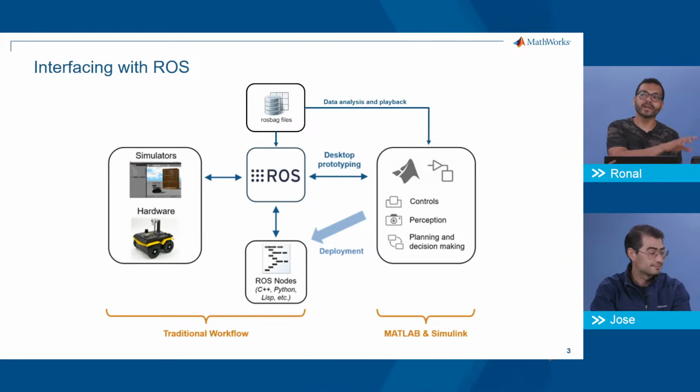Before you start working with hardware, I would highly recommend going into a simulation environment. Why? Well, one, first you have to get the hardware actually running to be able to do anything. That's going to take a long period of time. Second, whenever you want to test something with hardware, your battery should be charged, and you should have network communications, like Wi-Fi or some way of connecting. All these are just going to be blockades to actually getting what you want done. So I would recommend starting with a simulation environment where your experiment is repeatable.